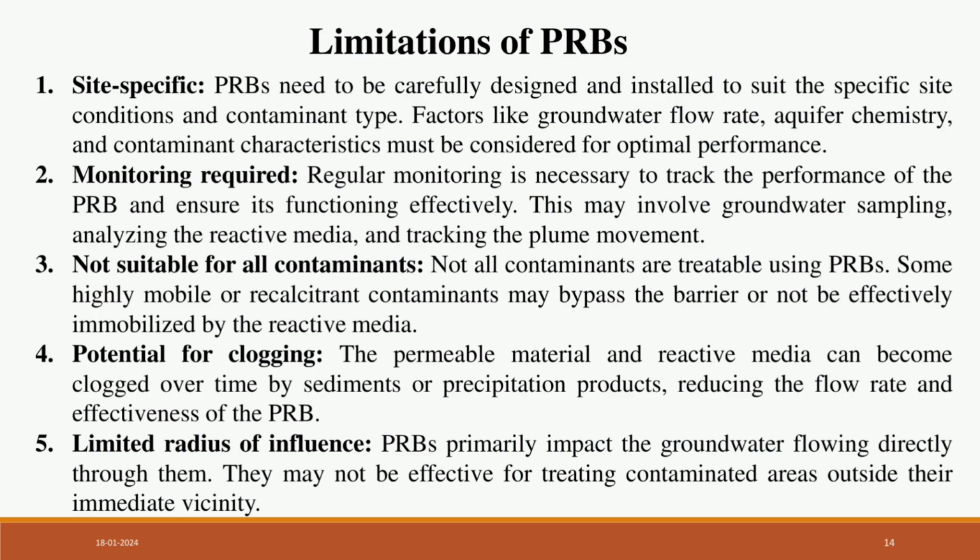Fourth one is potential for clogging. The permeable material and reactive media can become clogged over time by sediment or precipitation products. It results in the reduction of flow rate and effectiveness of PRBs.